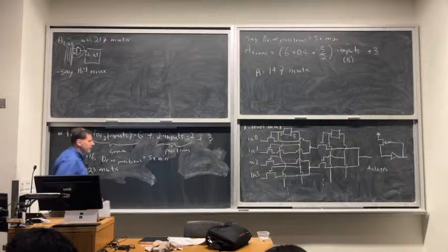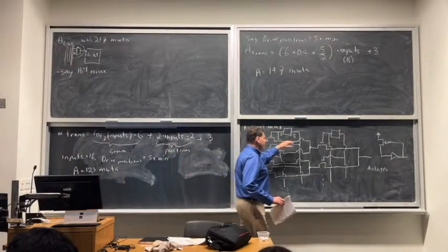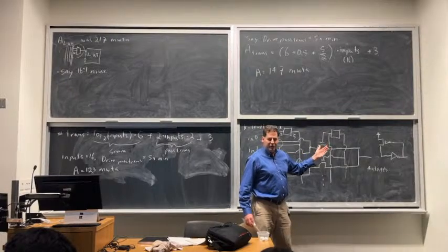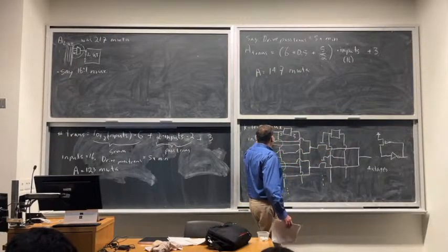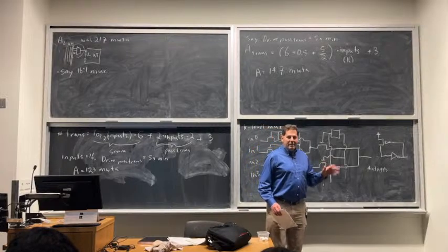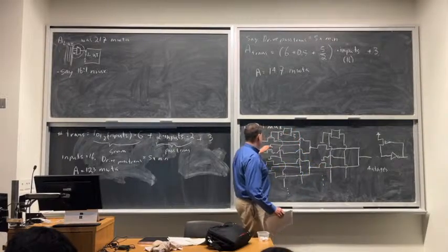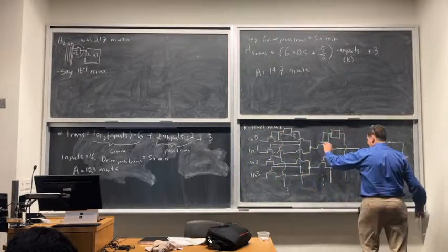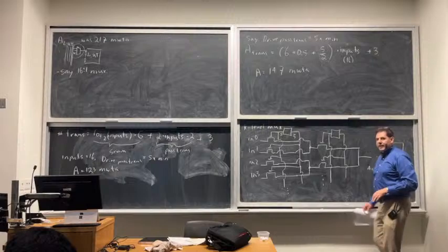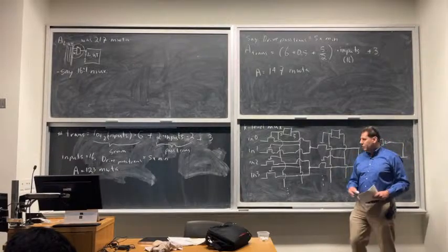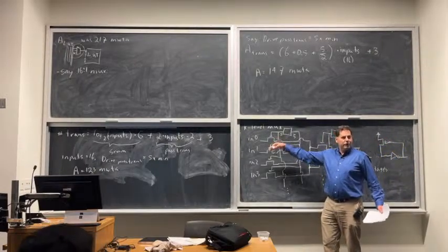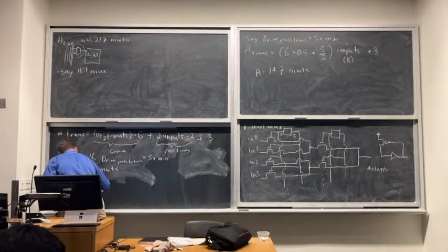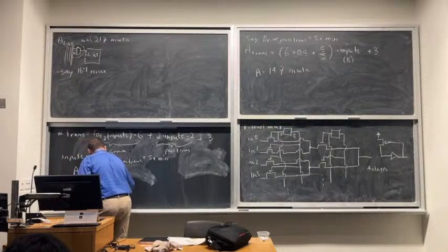So it's going to be worse because, again, to first order, when you're optimizing transistor circuits, you can just think of them as if they're resistors, because they are actually nonlinear resistors. So within their main operating region, they do actually behave like a resistor once you turn them on. So putting multiple resistors in series, and then you've got some capacitance that they have to charge at the output, is going to be slower than just having one transistor or resistor discharging that capacitance. So the switching speed is lower, so there's a trade-off here. Speed is slower.